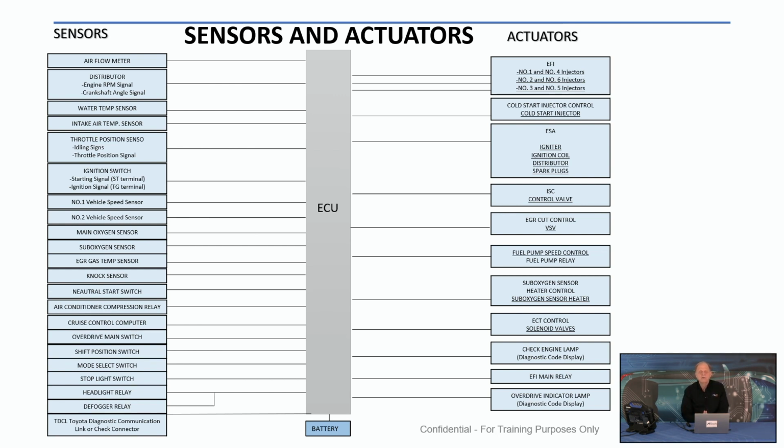Keep this in mind. You have to understand the sensor inputs related to what you're looking for. So fuel trim would be what? Mass airflow sensor, MAP sensor, throttle position sensor, intake and coolant sensors. And you would be able to look at what you would have a problem with. You have to understand there are sensors that will be related just to that code or whatever you're looking at. So again, if you were looking at code criteria on a particular code, it would tell you what sensors are related to the issues that you might have. So you might want to check those in conjunction. There's a lot of information out here. We're just going to kind of break it down to make it a little bit easier to understand, and we go to the next process.